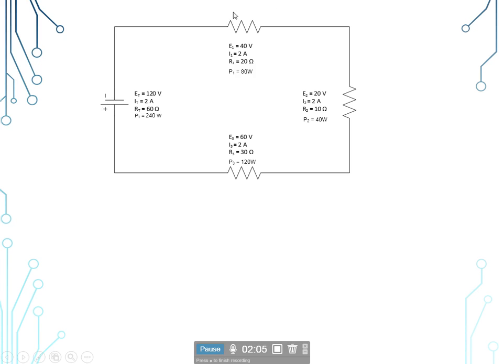Up here at the top we have that zigzag line. That is a schematic symbol for a resistor. A resistor is a load. This would be R sub 1, this one would be R sub 2, this one would be R sub 3. Even if they're not numbered, you can number them like that. Whenever I'm using subscripts, like the R sub 1, that subscript is just an identifier so that we know what component we're talking about. That way when we start getting good and bad components in there, we know what's what. If I use a subscript of T, that means we're talking about circuit totals.